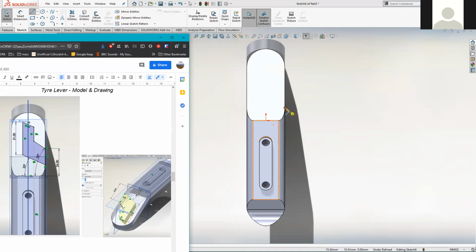So this is why the order that you create these features is relatively important. I believe this first point that we're about to drop in, that one on the sketch, is locked to the point at which this fillet feature, that we put on that edge earlier, must be there first, because we use its endpoint there as a reference to lock our sketch to.